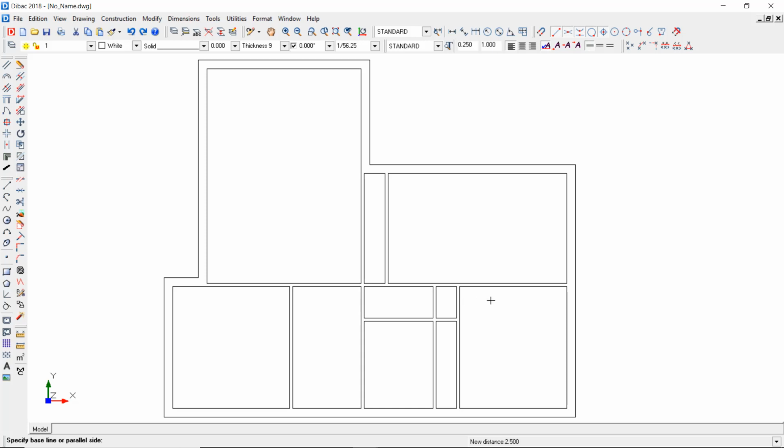I can use the eraser tool to delete sections of walls. If I delete one section at a time, the intersections and corners will be fixed automatically. To do this, click on one of the two sides of the wall section and then right-click with the mouse to delete it. To delete other section, do the same process. Left-click on one of the two sides of the wall and then right-click to delete the selection.